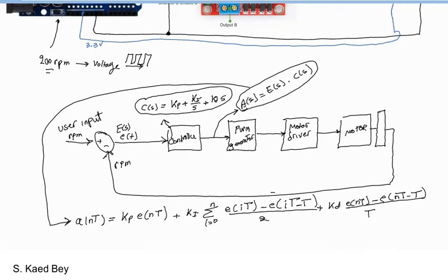After implementing the difference equation in Arduino Uno, we will try to find the optimal values for Kp, Ki, and Kd. There are multiple methods available. The first one is the trial and error method, which we will be using here. There are other techniques like the curve techniques or the Ziegler-Nichols method. However, in our work here today, we will simply do the trial and error method.